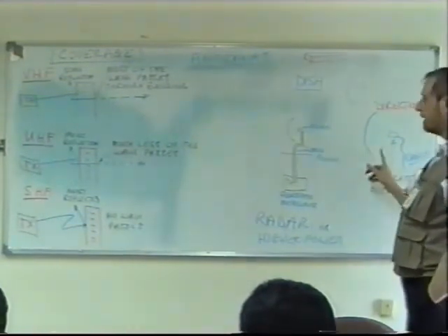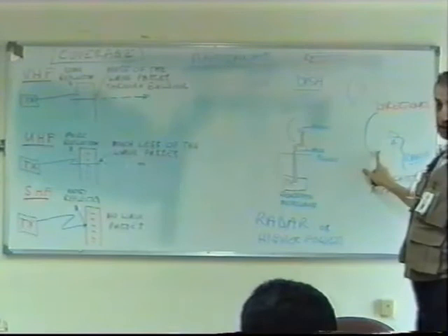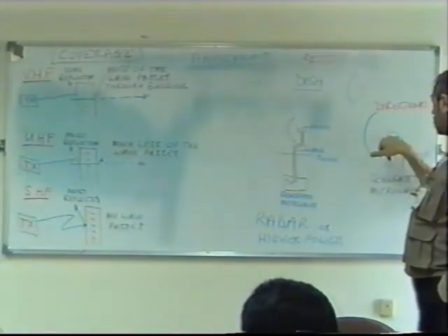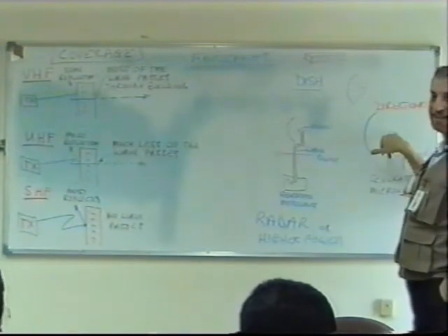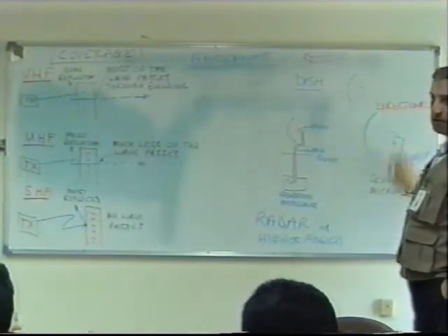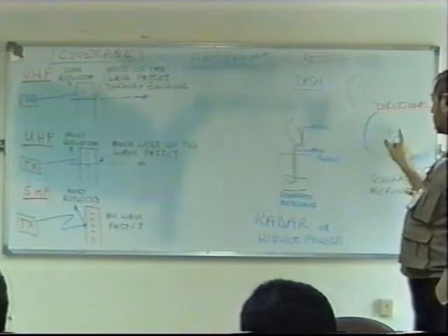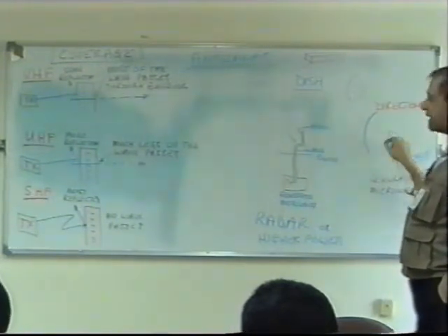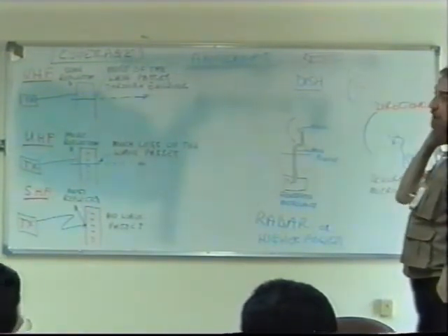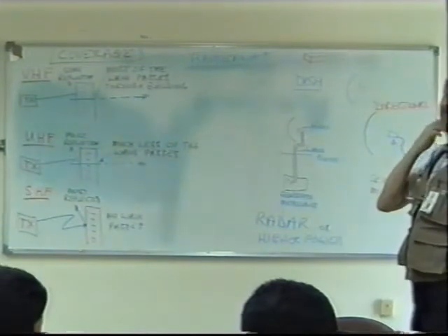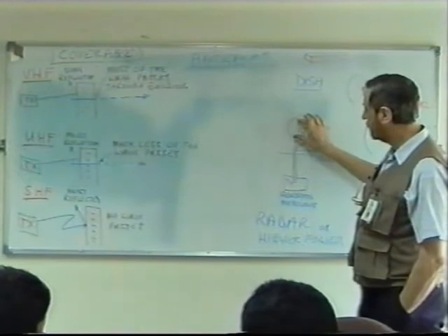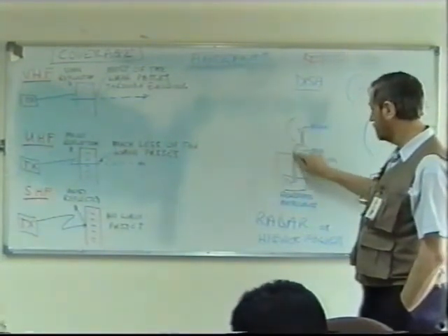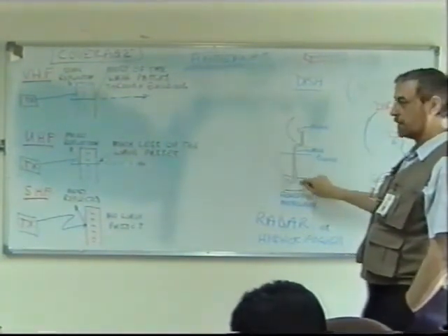The most common arrangement for communications is this, where the microwaves are generated in front of the dish. They're actually generated here. They're not generated remotely. So part of your transmitter is actually here, in front of the dish. And it's the same for the receiver. Here, the received microwaves are focused into the horn and then they're directed down to the receiver.